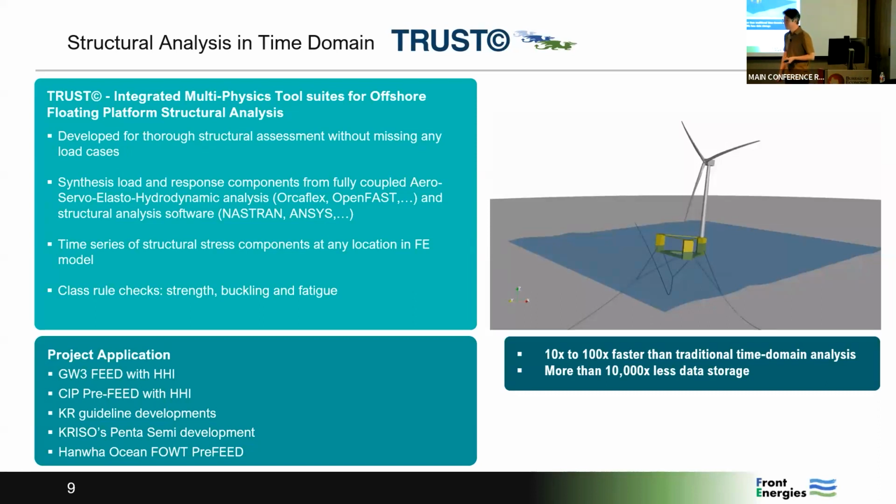Any other question in chat? Could you add more branches to the mooring? The number of mooring lines is very expensive, so we would like to reduce the number of mooring lines. That's the main purpose, which is why we have the Y shape. Otherwise, definitely, we can put in additional mooring lines. It's a very conventional mooring line: each column has 2 mooring lines, so in total 6 mooring lines, and we can configure that.